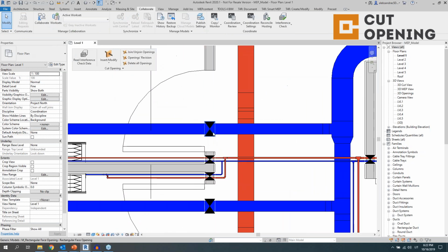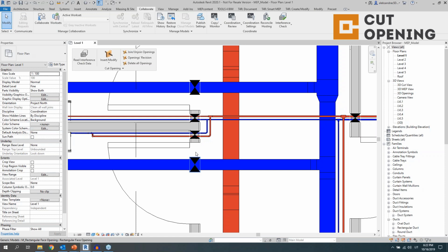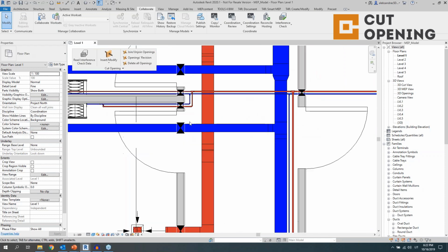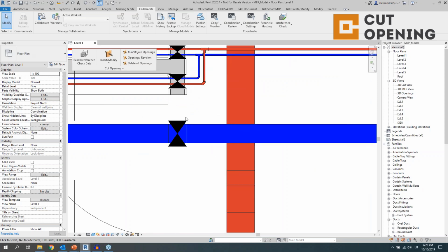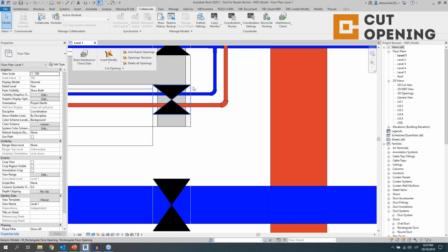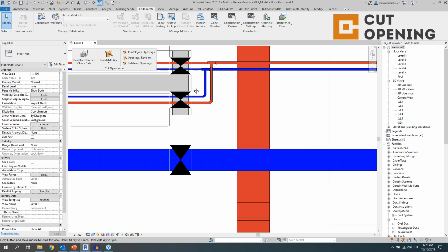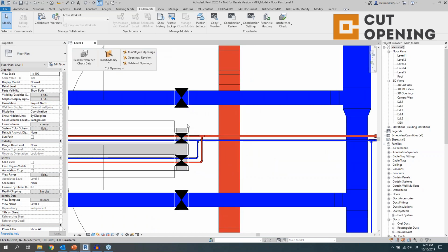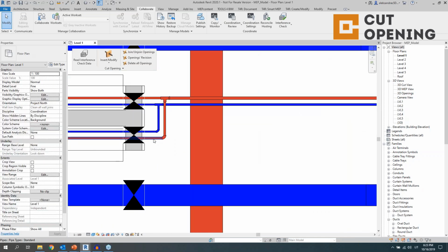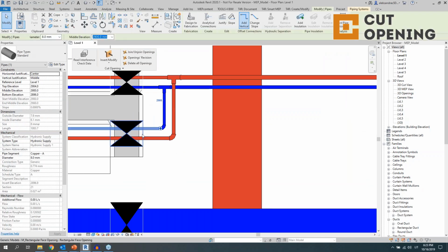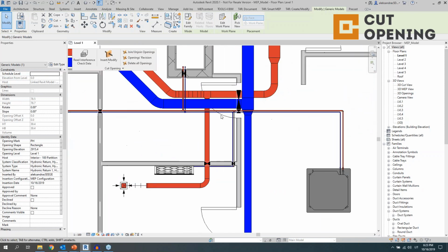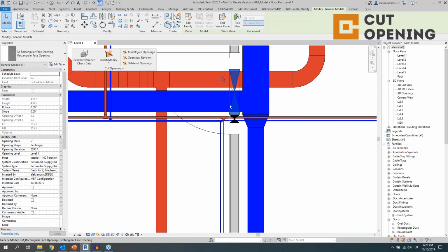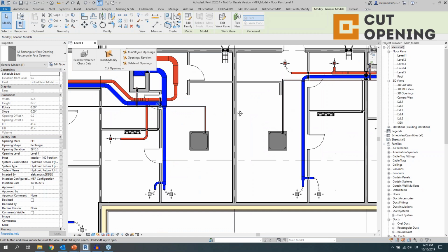That's on the first floor, everywhere where MEP services intersect the wall, openings are created. I've set everywhere cut offset 20mm, so it would be easier to follow. And as you can see, everywhere is the same distance from service to the opening. And where two pipes are going, opening is of course joined, and we have one opening. Also here, openings are joined. This is further because the different level of openings.